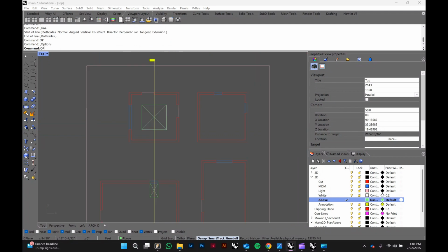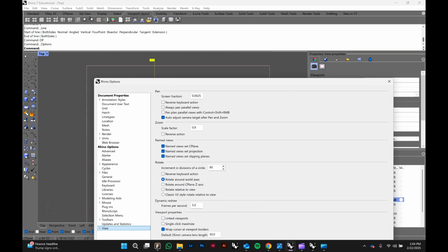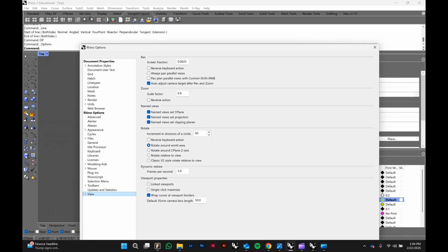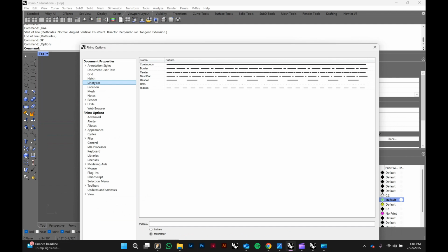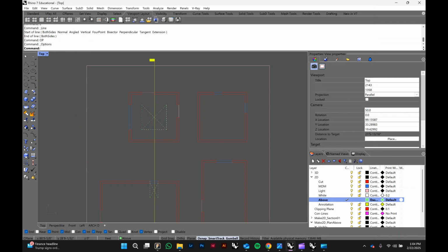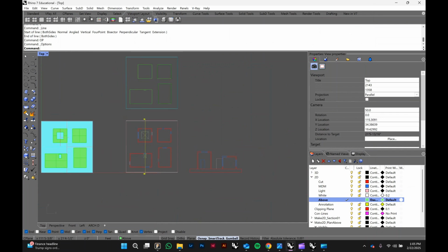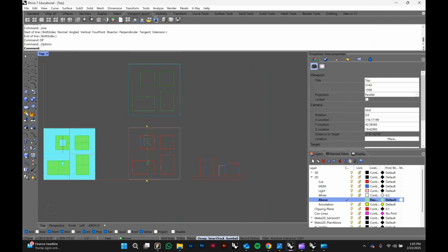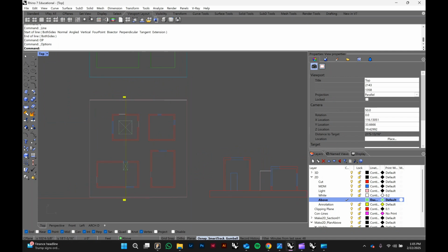And you'll see it's super small dash. So another quick tidbit, we're going to go to options. You're going to get the pop-up window like this. I'm going to go to line types, and let's bump my scale up to 16. Let's see that. Perfect. Cool. I'm happy with that. And yeah, I think that is pretty much it for setting up your plans.